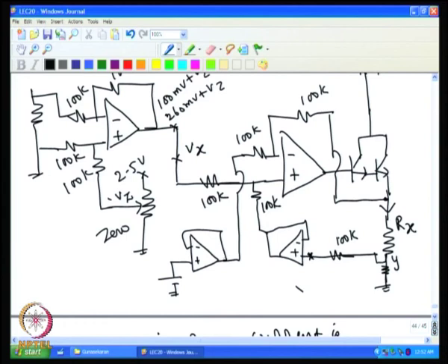By connecting this output, the required voltage can be varied by varying this resistor. Any voltage you want, because your 2.5 volt zener is there, can be tapped by varying these two resistors.